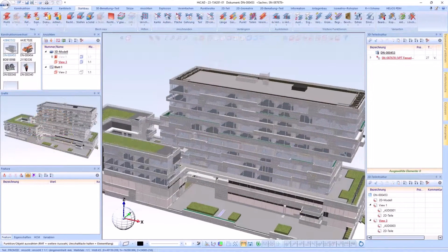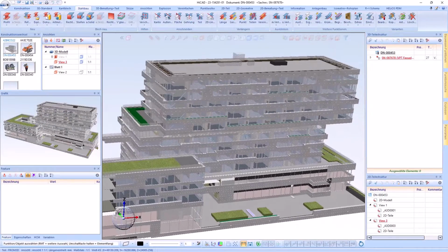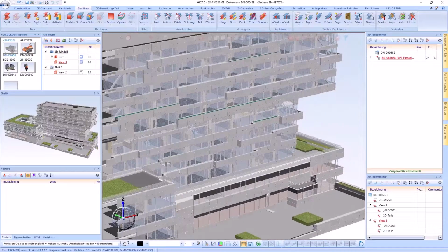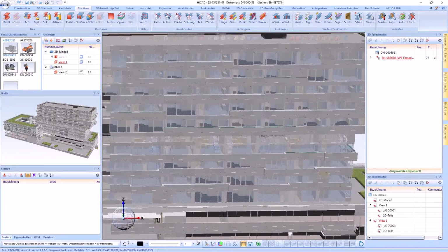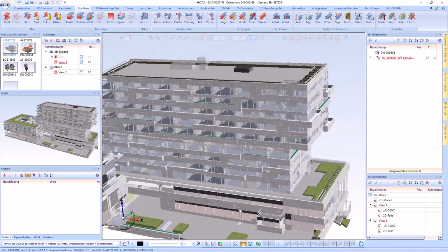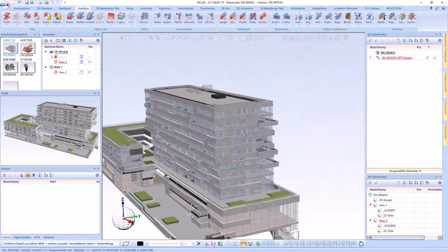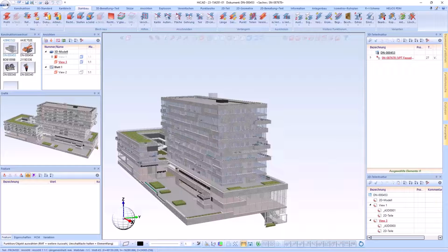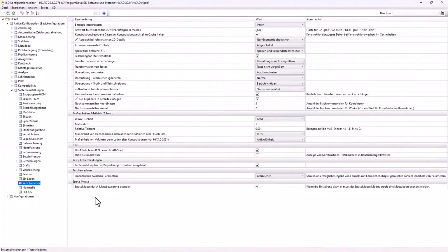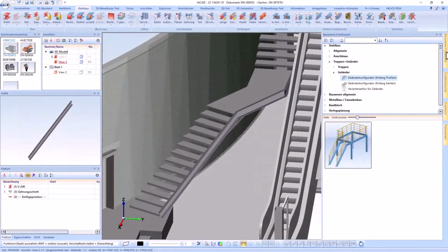When moving and rotating using the SpaceMouse, a view calculation is performed as soon as the controller cap is no longer deflected. This leads to frequent waiting times for larger drawings. This behavior can be changed via a configuration entry so that the calculation only takes place after a mouse movement. After the update, ending the rotation with a mouse movement becomes the default behavior.